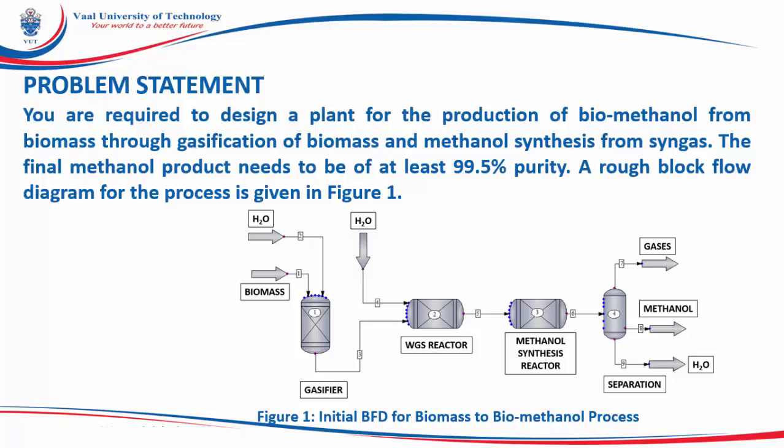This is not a flow diagram. The process flow diagram will emerge from your design, but this is a simple concept to indicate to you of the possible process units. This block flow diagram will give us a starting point. Please note that as details emerge, the flow sheet will have pumps, compressors, heat exchangers, separators, recycles, and other units, as well as process layout schemes that will be dictated by the process synthesis procedure.